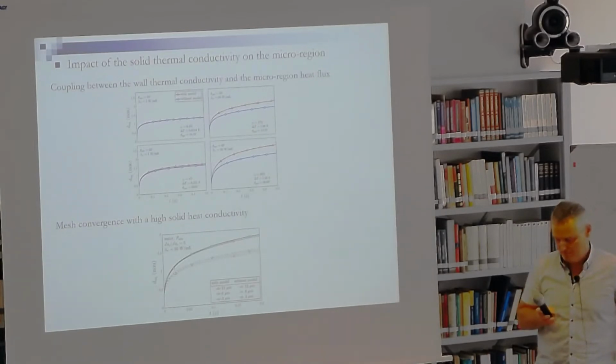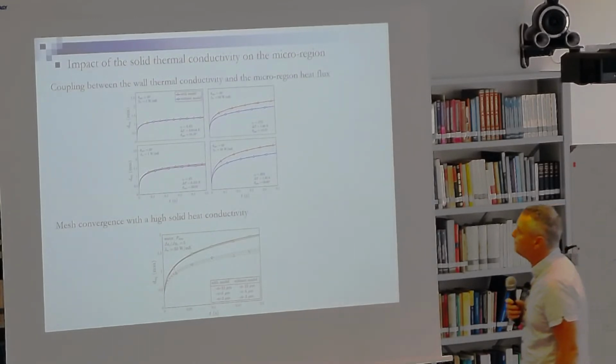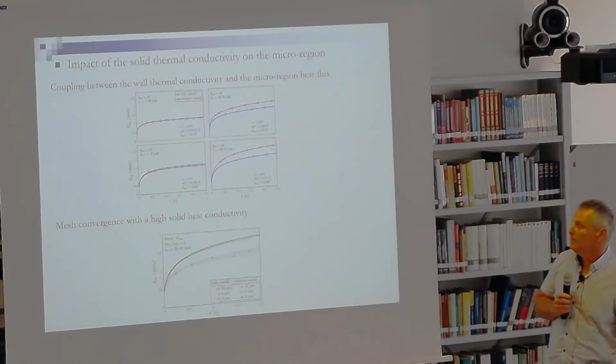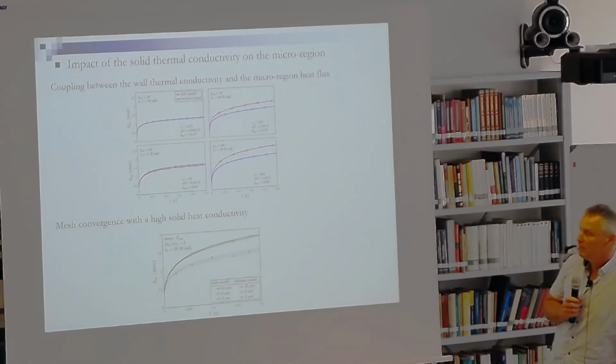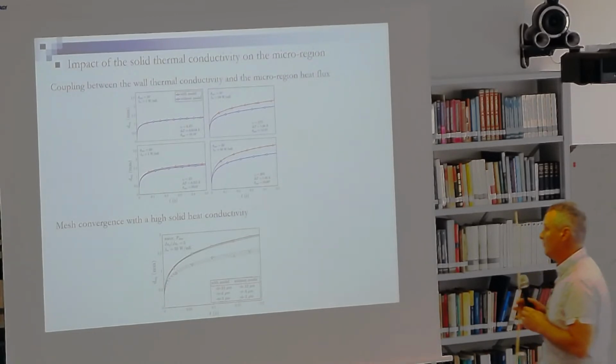Yeah. So, in my understanding, having a higher wall conductivity will be closer to the theoretical condition where the models were developed for. Because these models were developed for a constant wall temperature, so essentially an effusivity that tends to infinity. So the model should be more realistic when the conductivity is infinite and the effusivity is infinite. So, how do you explain the fact that without the model you have very good agreement and with the model they come apart?